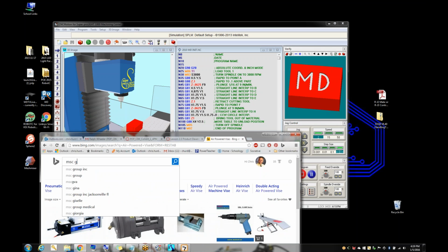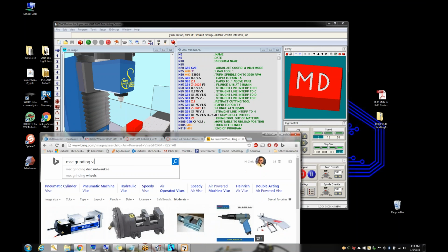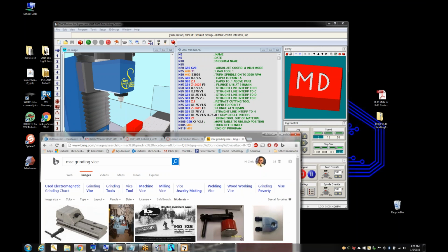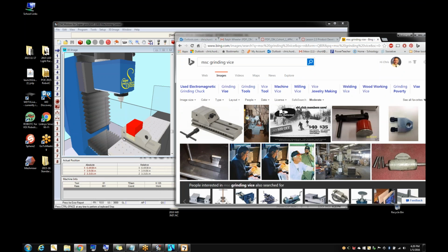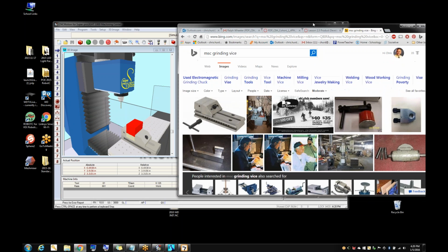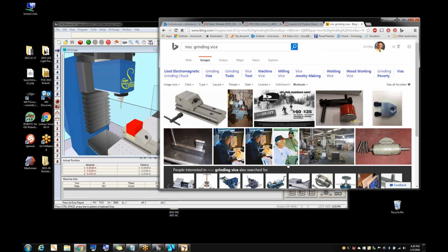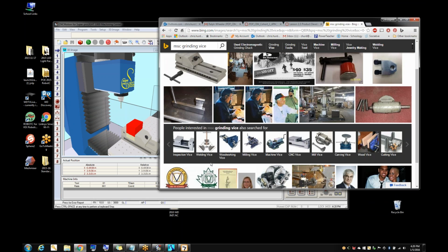I have two of the pneumatic vises, and the very first thing I did was yank them off there. Yep, and they take up a lot of room, and you have to be careful because that hydraulic cylinder, sometimes if you put it on incorrectly, the cylinder's sitting off here. The way they've got it, it should actually be up against the left shield. The vises are designed poorly. Their static vise, for us, the majority of the time should be on that front right or front left corner, and that's exactly where their cylinder is. It's just a bad placement. If you put it where they think it should be, that's a wonky place to put your origin.